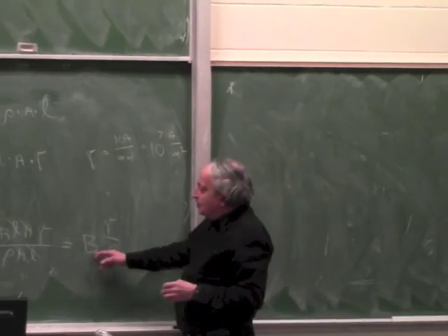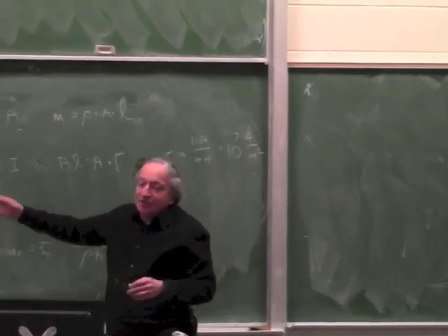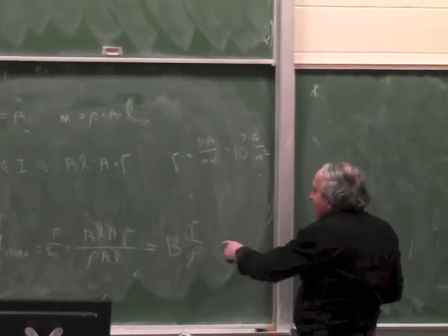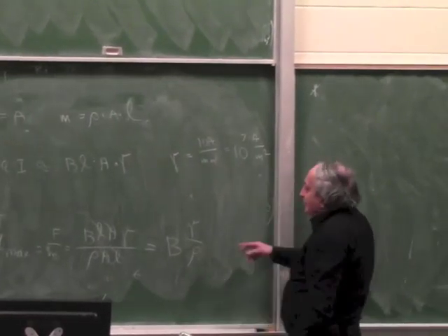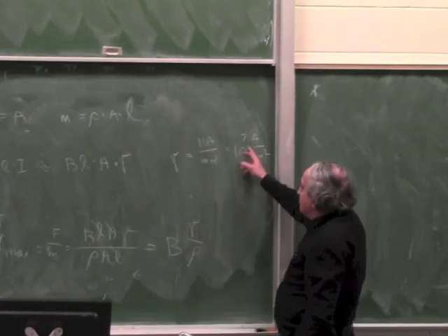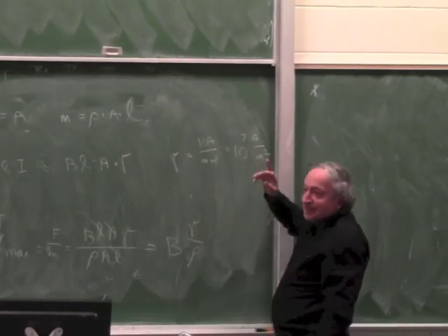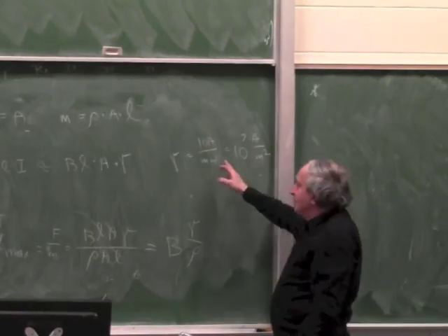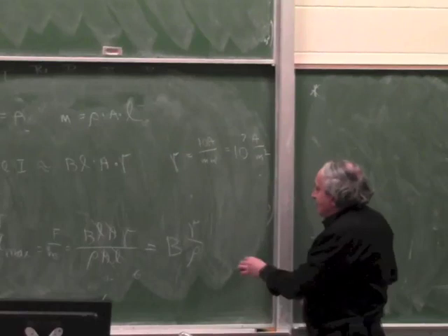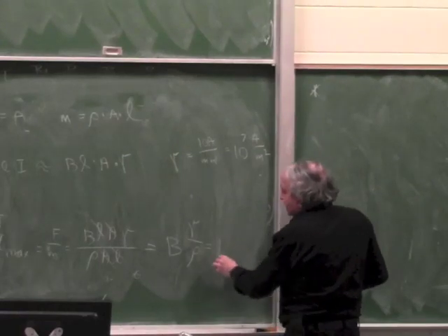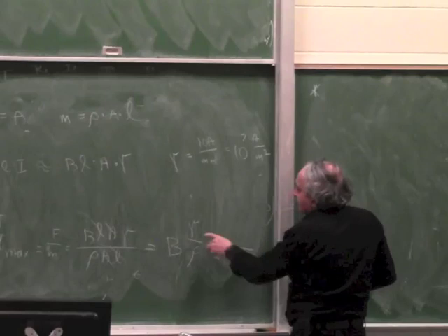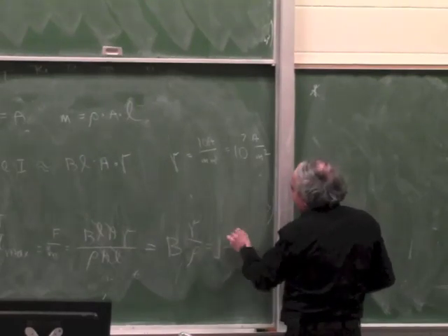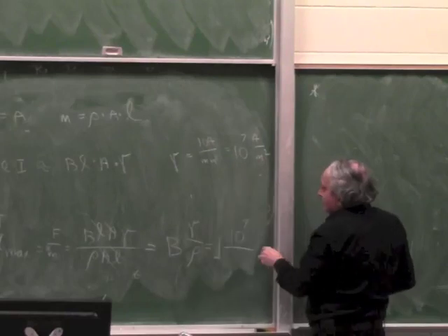You can only get so much B because of air gaps and because of the best magnetic material we have today. This can only be about 1 Tesla. Now, gamma, because of heating, cannot be much better than that. Steady state. Of course, if you give it a single pulse, momentarily, it can be much bigger. But steady state, you plug in the numbers, you'll get 1 Tesla times gamma, 10 to the 7th amperes per square meter, divided by rho.